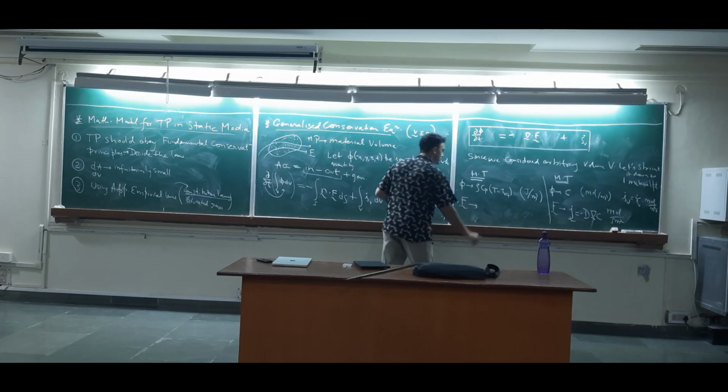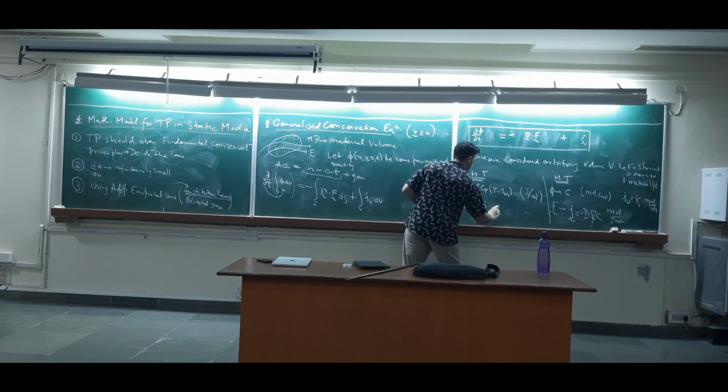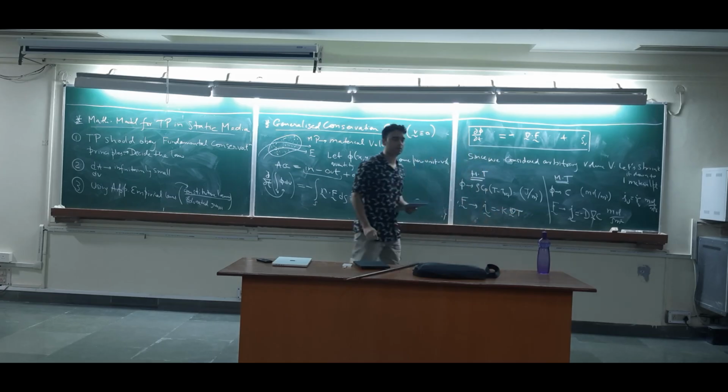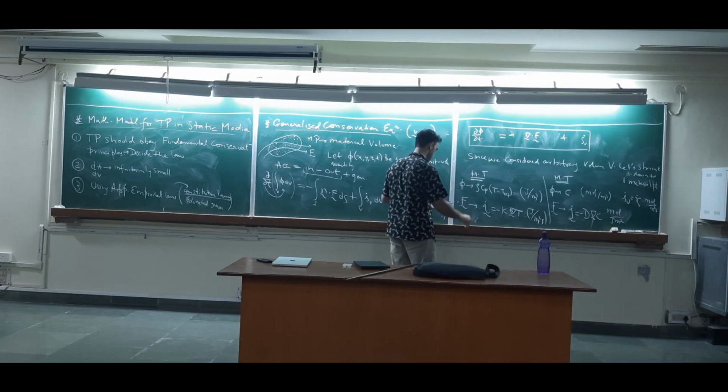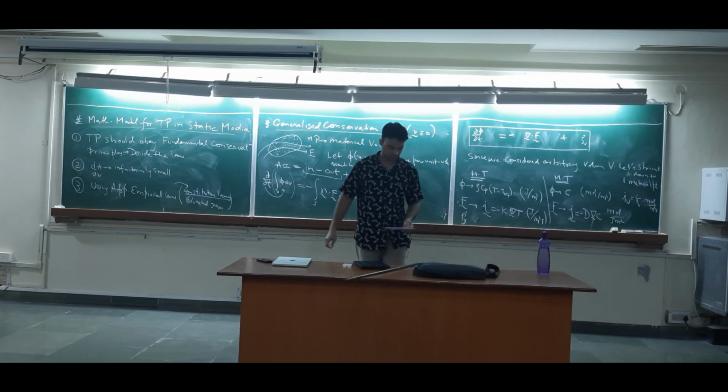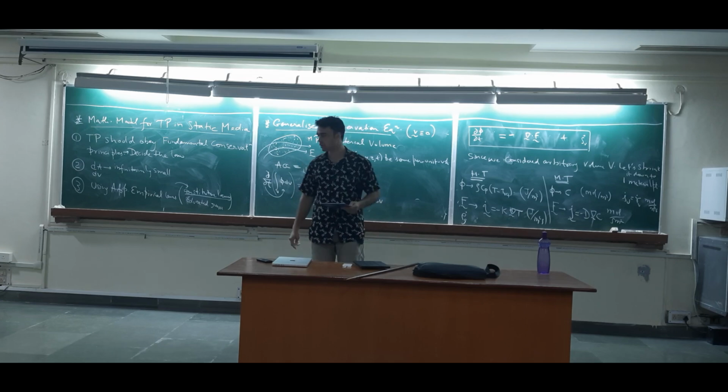F is q dot, equal to minus K del T. This is F, joule per meter square second, and S will be E gen dot. So now we can plug in for each case and find our diffusion equation for heat and mass.